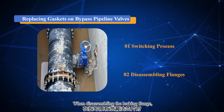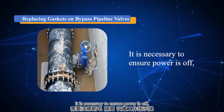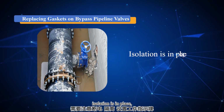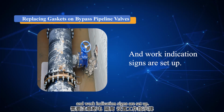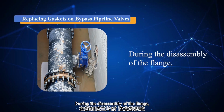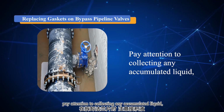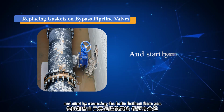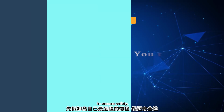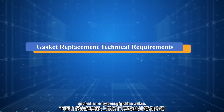When disassembling the leaking flange, it is necessary to ensure power is off, isolation is in place, and work indication signs are set up. During the disassembly of the flange, pay attention to collecting any accumulated liquid, and start by removing the bolts farthest from you to ensure safety. The following is an introduction of replacing gasket on a bypass pipeline valve.